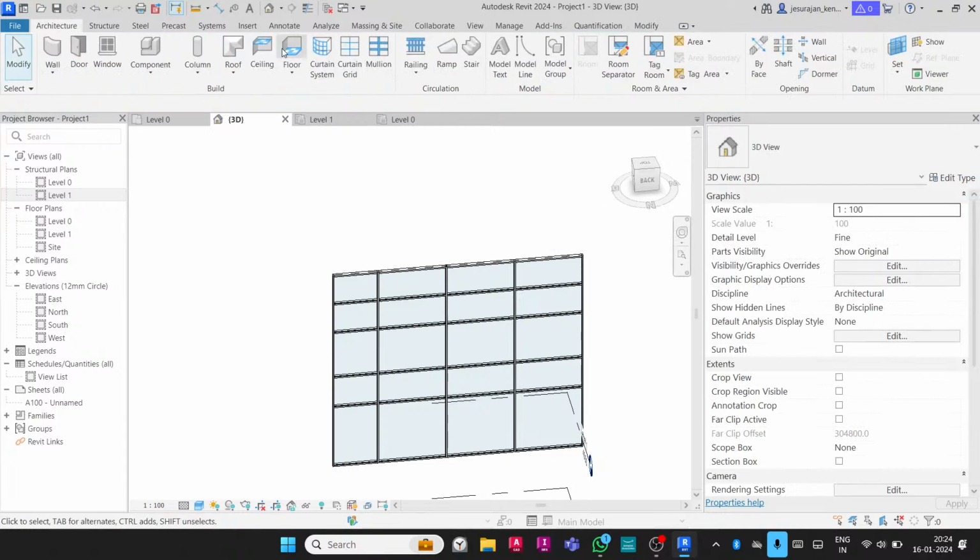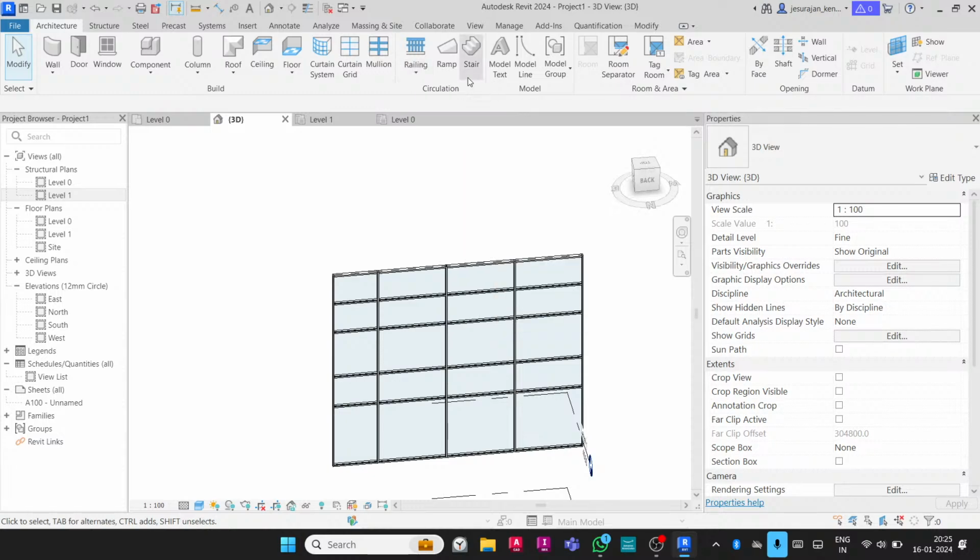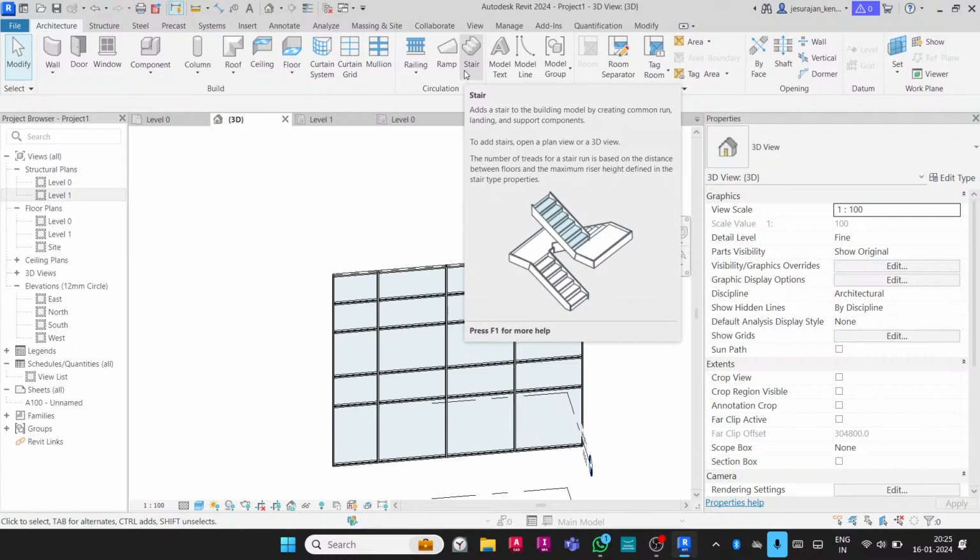Okay, so we know till here. And then we saw a sample configuration about the handrail, right? The top rail, non-continuous rail, start post, end post, corner post, and baluster configuration we have seen. We have also checked a sample Revit file, right? Then we have seen how to draw a staircase and how to draw a ramp. How staircase and ramp works we have seen.